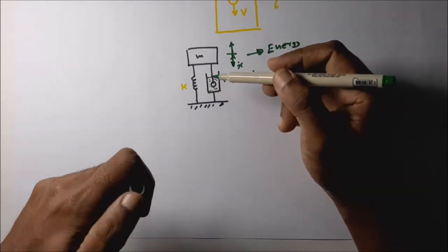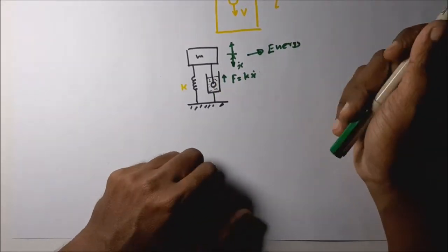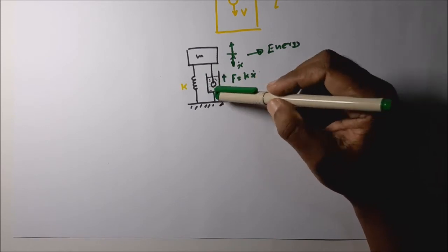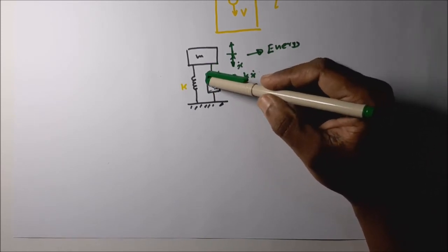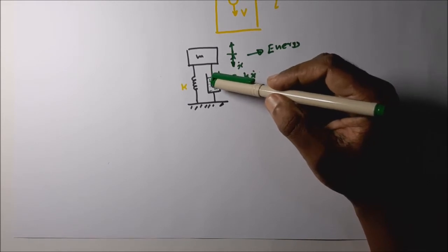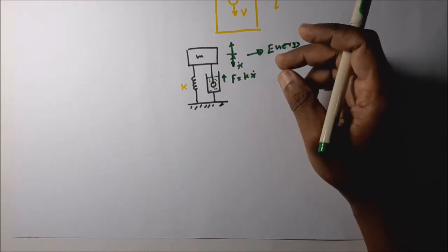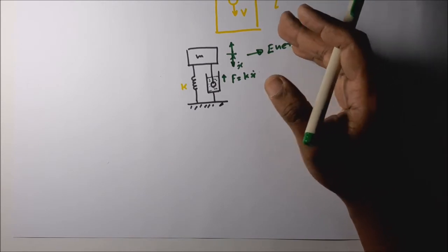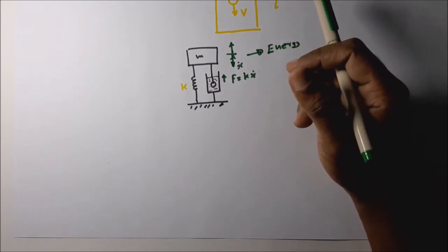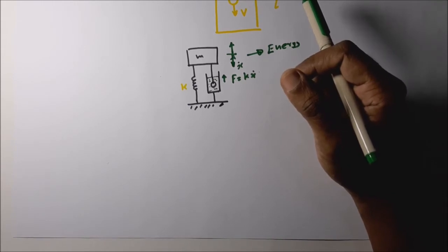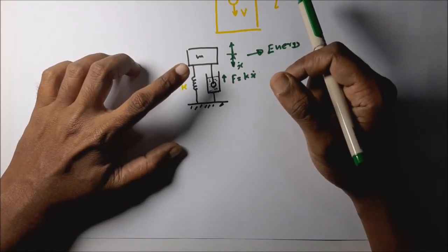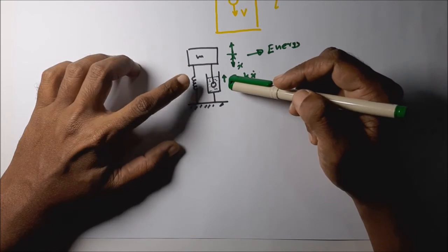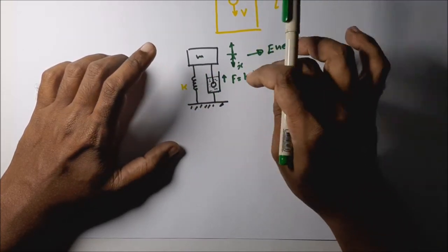Okay, this is the basic principle used to design vehicle shock absorbers. Vehicle shock absorbers also have this kind of viscous fluid, and instead of a moving object, the fluid is transferred to another chamber through a small orifice. The same thing happens when it transfers through the small orifice. Certain energy is consumed to do this work. Then in detail we are going to discuss this viscous damping later. We are going to mathematically model this kind of system later.